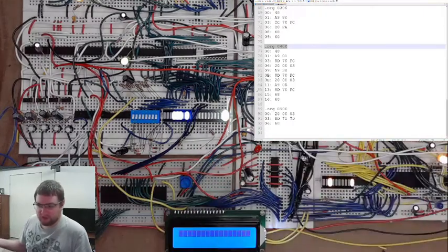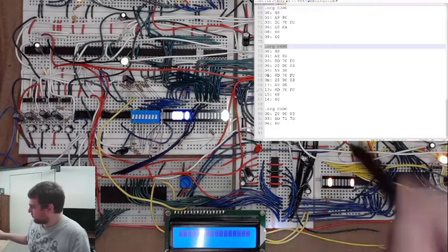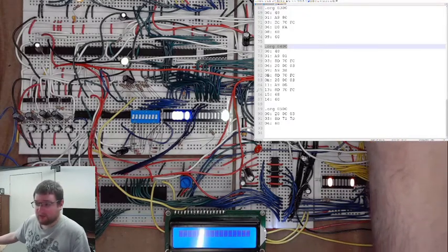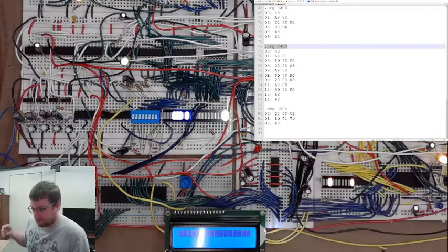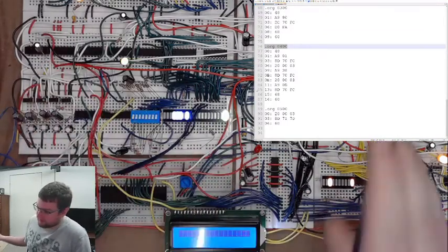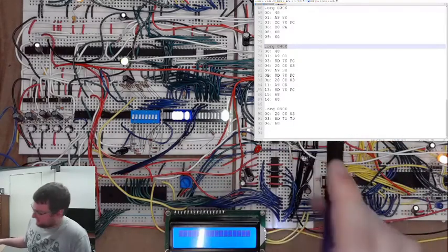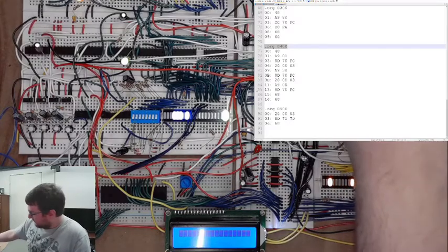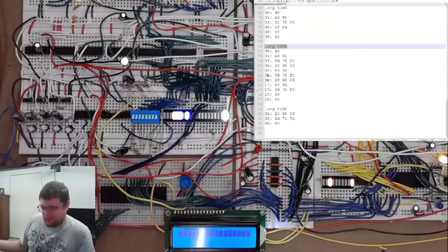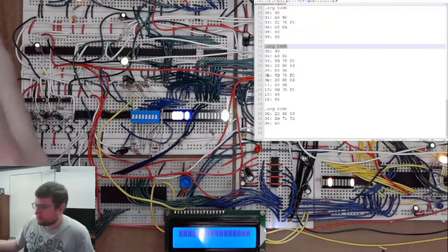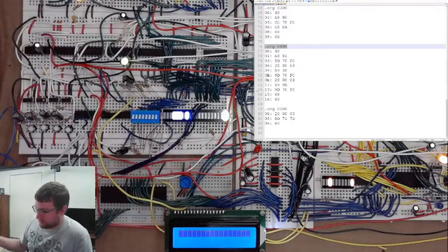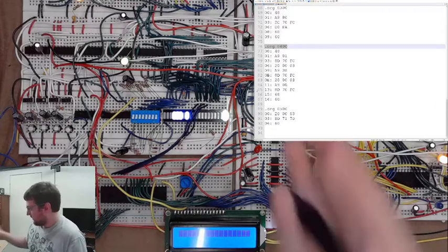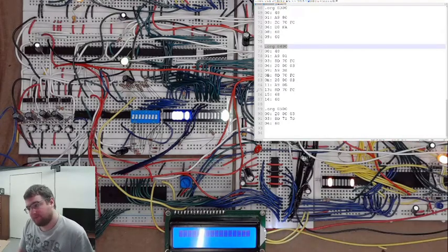you can read it, so there's no point in ever doing interrupts. Just do something for those 8 clock cycles that you know you're going to have to do, and it'll be done. Because if you're running that at 20, you're running that at 14, you're basically running it at the same rate. You know every instruction is going to take you at least 2 clock cycles. That means that you're running at about half the speed. And so that'll take 8 clock cycles to output every bit.